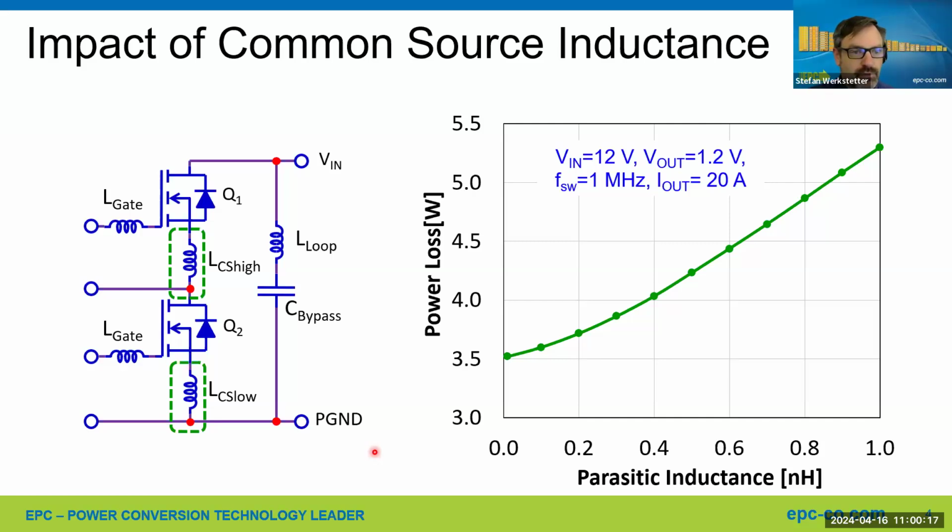Okay, and last question for today's Q&A. Internal GaN diode usually is poor in performance. Is it recommended to add an external diode between source and drain? Okay, poor in performance in terms of voltage drop. It's very good in performance for switching, because we don't have reverse recovery. In terms of voltage drop, it is between 2 and 3 volts, depending on the current of the operation.